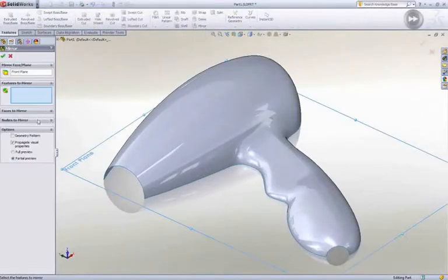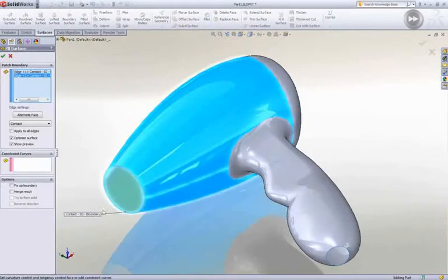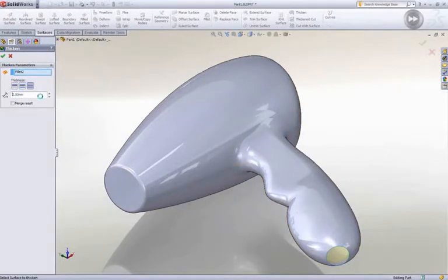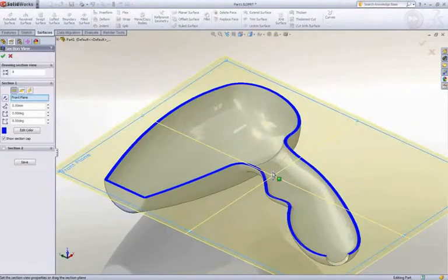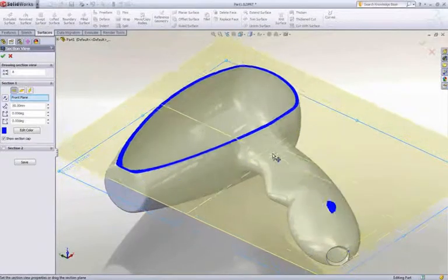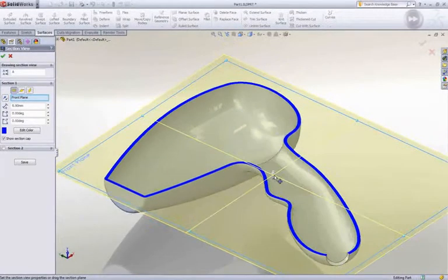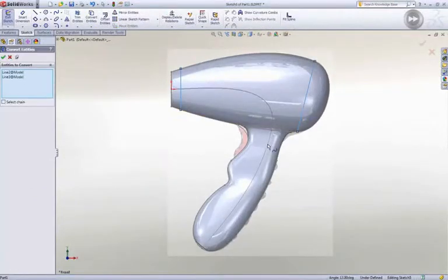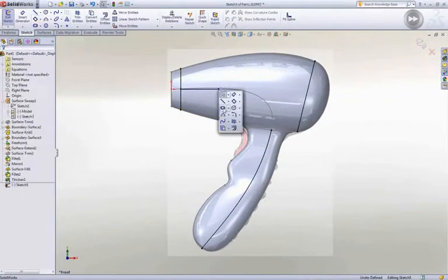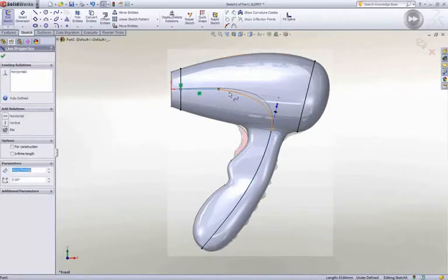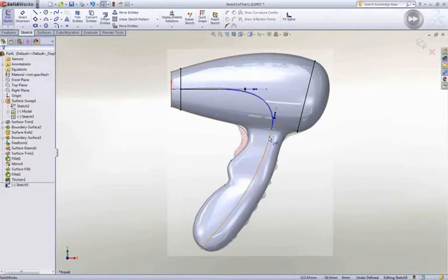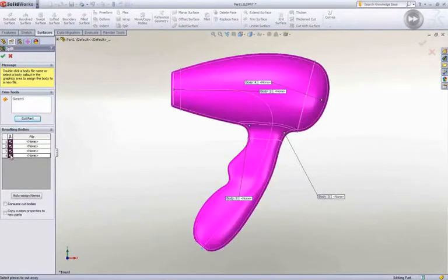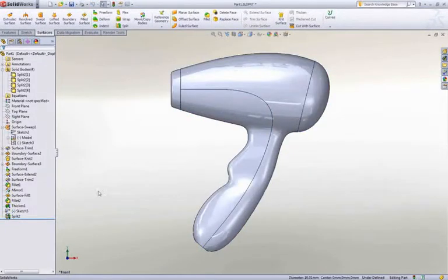The aesthetic design of the product is now complete, so we can start to add manufacturing details. Since the design is all driven from the same model and in the same environment, design changes are fast, predictable, and easy to do. This solid model of the design can now be split into individual components and either saved as an assembly or kept as a multi-body part, allowing you to continue adding features such as lips, grooves, and bosses, whilst ensuring all the parts fit together perfectly. Each part can then be detailed independently and also be used for tooling design.